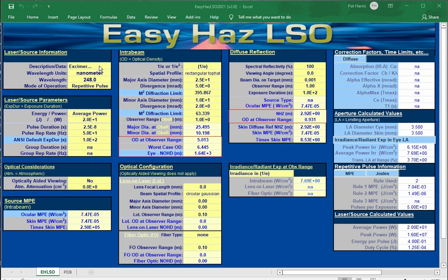This laser is a little more to deal with in terms of the gas mixes and keeping it aligned and keeping it running. Nowadays, most people, if they need that UV wavelength around 248 to process materials, have gone to a solid state laser, a YAG, and by pumping crystals and looking at the third and fourth harmonic, we can generate 355 nanometers and 266 nanometers in a much easier way, easier to maintain and much more stable in its running.